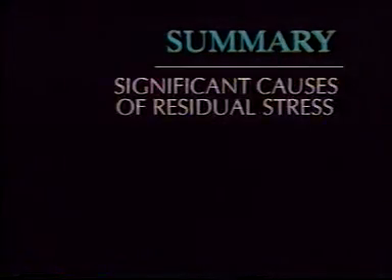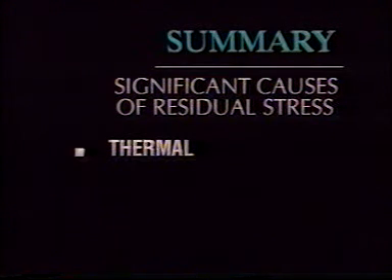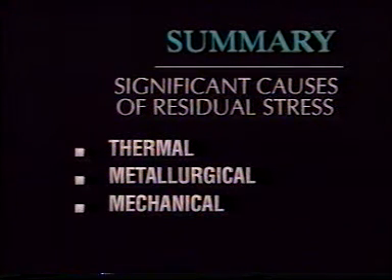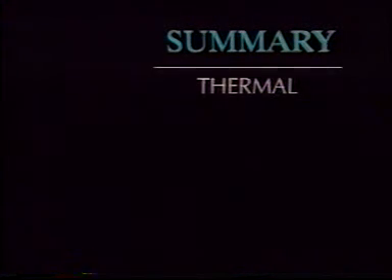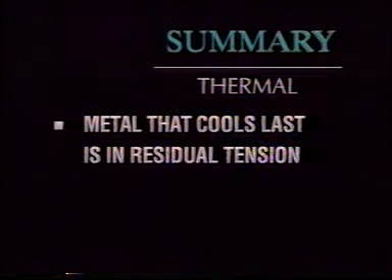In summary, though, we should point out the few basic principles that will help guide you in your study of residual stress. The most significant types of residual stress are caused by thermal, metallurgical, and mechanical factors. Thermal residual stresses are induced because the metal that cools last is in residual tension.